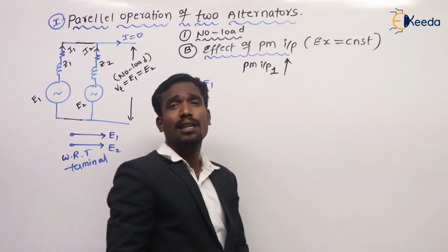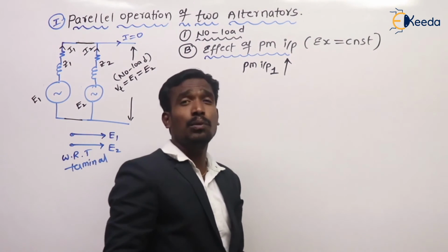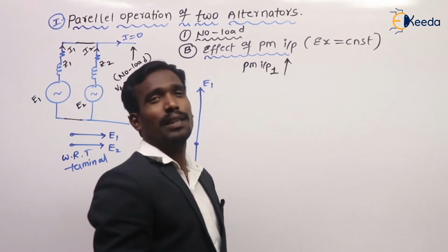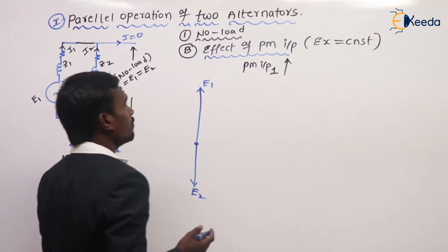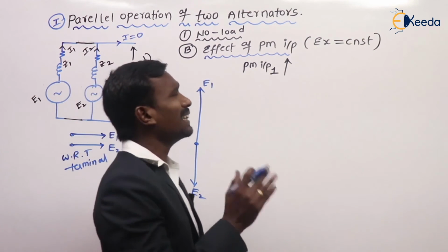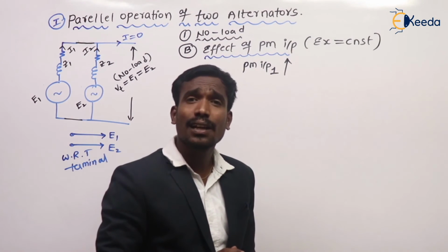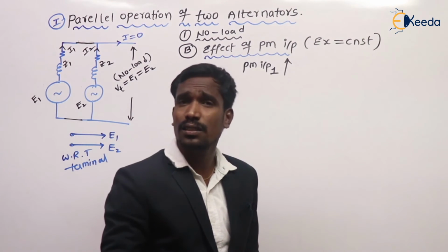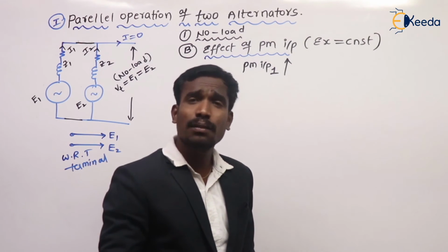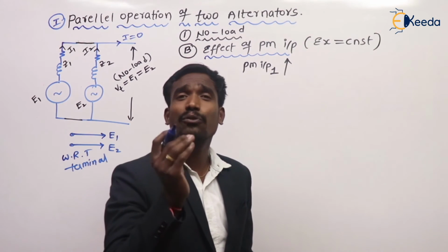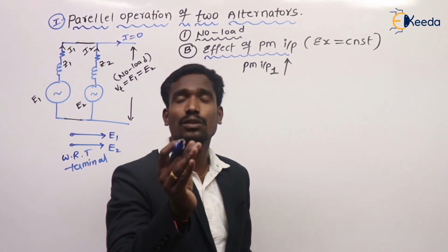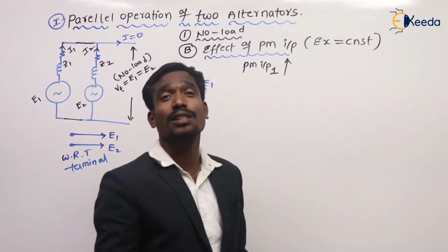When the prime mover input of machine 1 increases, ultimately the frequency changes, the EMF also changes, and the phase sequence and phase shift also change.